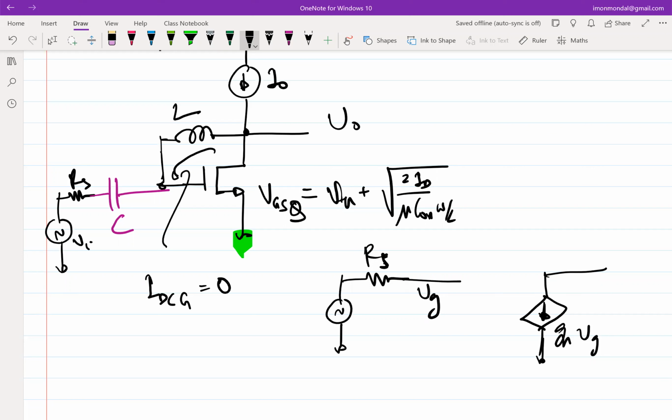At high omega, your impedance is higher. And the values of L that you get on chip are typically of the order of few nanohenries at max. You don't get more than that, which means you have to go to multi-gigahertz to get any appreciable value of inductance. So if you are operating in the sub-gigahertz range, generally you will not see inductors being used.